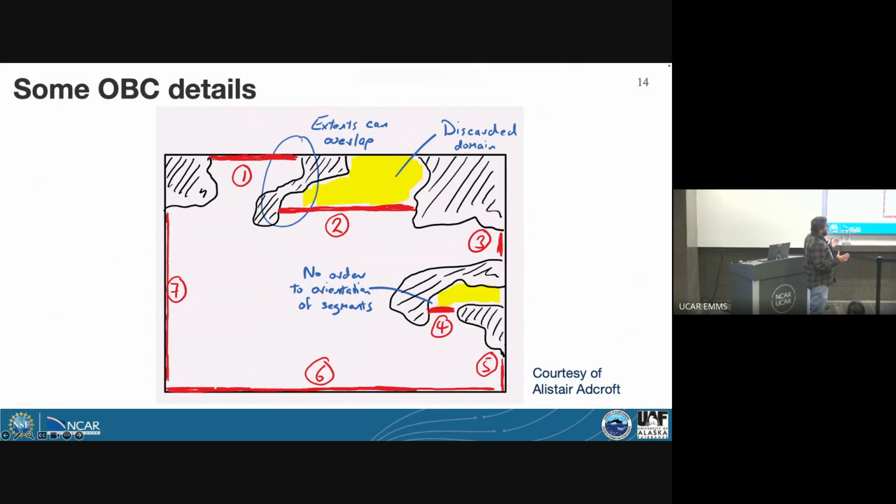Typically, in an ocean regional model, when we think about open boundaries, we think about the edges of your domain. In MOM6, you have the ability to prescribe the boundary inside, and essentially you can think of the OBC as just a line along which you are going to solve a different set of equations, your OBC equation, and not something that is on the edge.